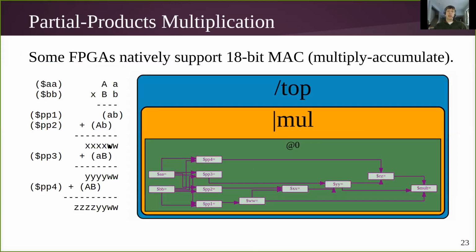Okay, so I hope that exercise went well and you were able to create your own pipelined logic. We're going to look at one more pipelined example. This example I'm introducing so that we can get into verification benefits. This example is one that I took from somebody's blog post where they were talking about how you can implement a multiply operation on an FPGA. So an FPGA fundamentally supports a multiply accumulate logic block, or a DSP block, and that block supports an 18-bit multiply operation.